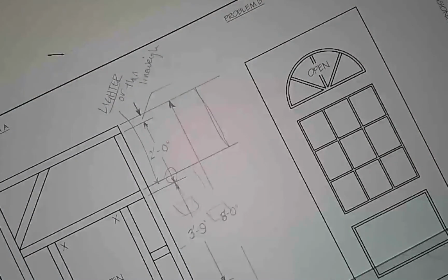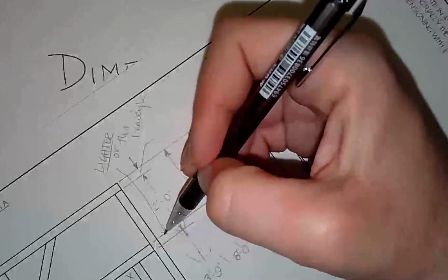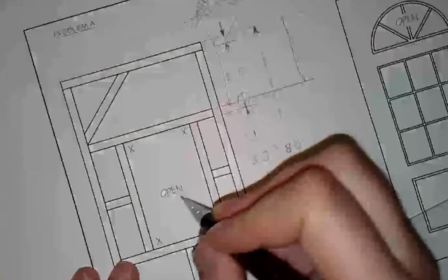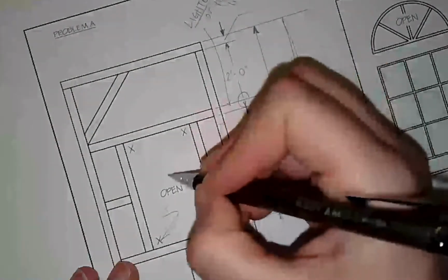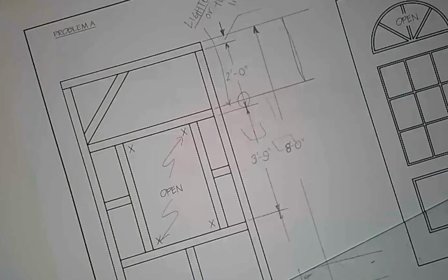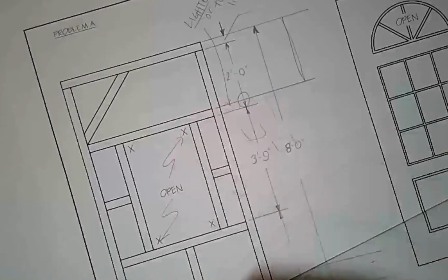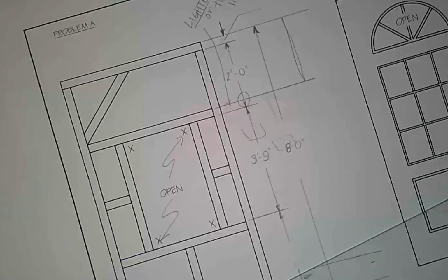We talked a little bit about a leader line, right? So this is a leader line. This is actually also, what I've done right here is a leader line. Sometimes if you have something like this which says open, you would draw a set of leader lines like that to indicate that that whole area is covered or open in this case. And you can do the same thing with a material choice. So if you're talking about a wood floor, you can just write wood floor and then do the little zigzaggy squiggle leader lines with the arrows on each end, and that indicates that. Let's see.